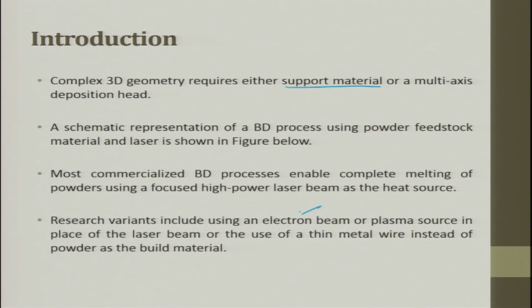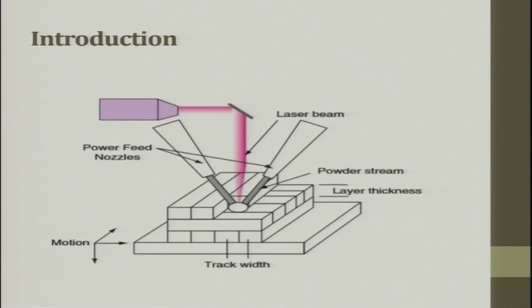See, the advantage of electron beam is that it is more focused, but the disadvantage is it needs vacuum. Today we talk about low pressure or low vacuum systems for developing, and today electron beam is competing with laser beam in this beam delivery system in the rapid manufacturing way.